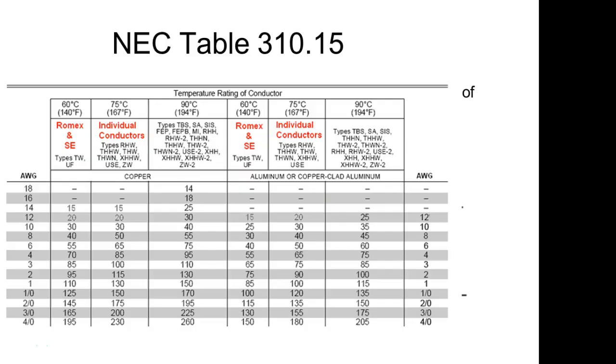So here's the ampacity chart coming off the National Electrical Code. They rate a 14 gauge wire at what? 15 amps if it runs these insulators, 30 amps if it runs those insulators, and then it's not rated at this right here. All these up there are different types of insulators that an electrician would understand.